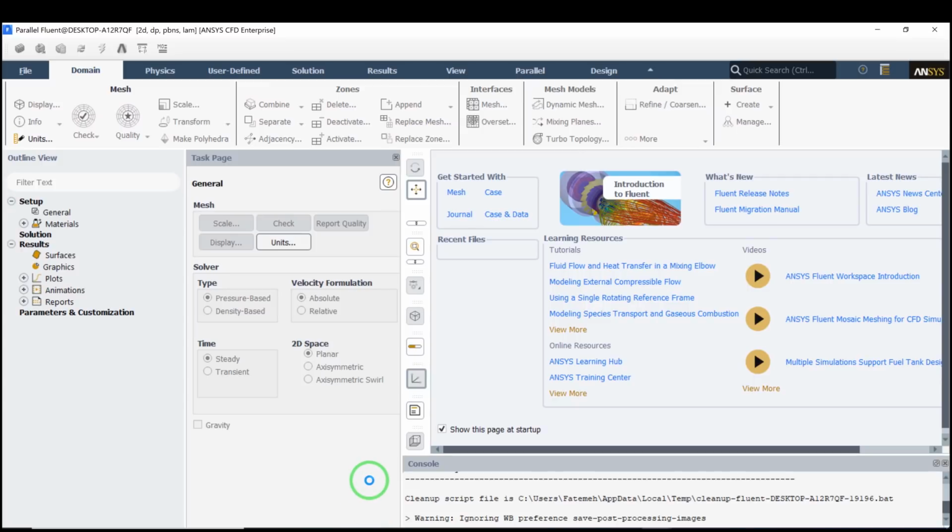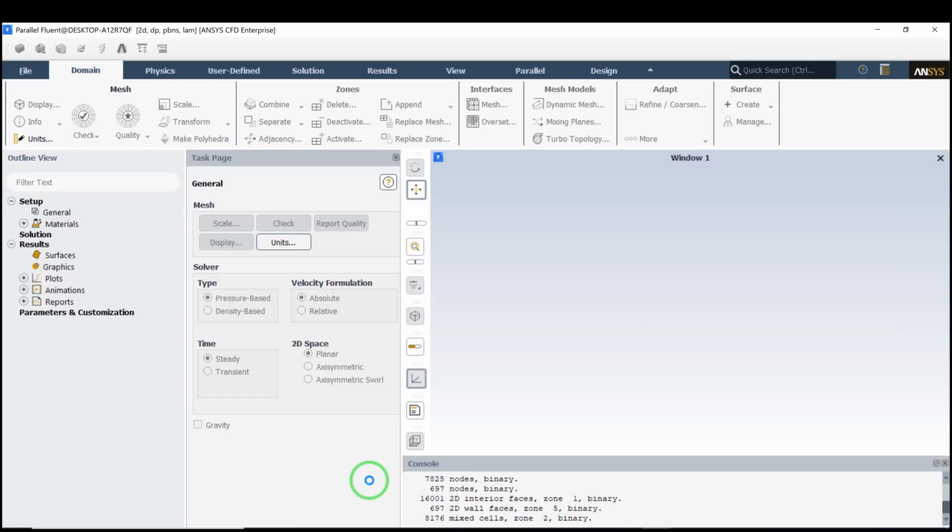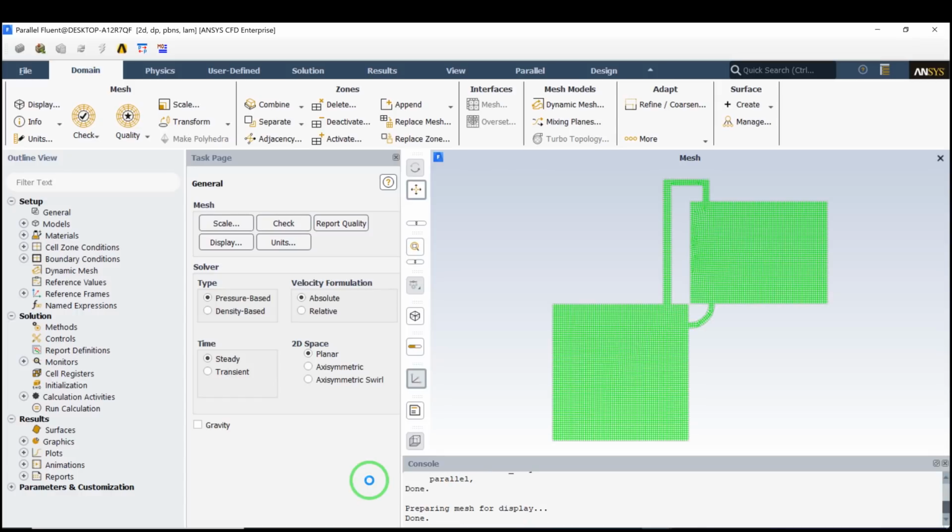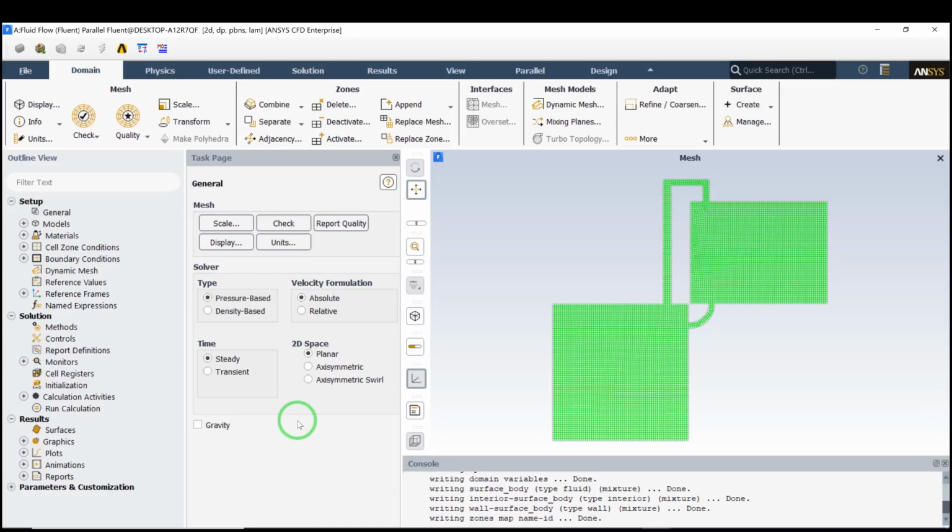So what will I do? I will use the volume of fluid simulation. Using the volume of fluid model, I will use the laminar model to expedite our simulations. You can use turbulence, but you need to see if the flow has a turbulent nature or not. You need to look at the Reynolds number. So this is a transient simulation which has gravity. This direction was the y direction, so we will have minus 9.81 for the gravity.